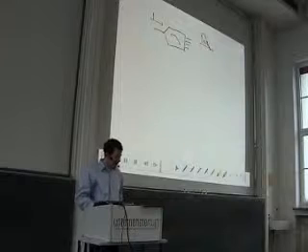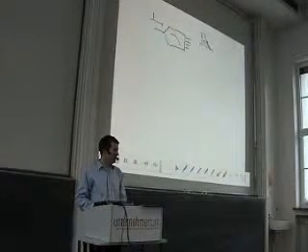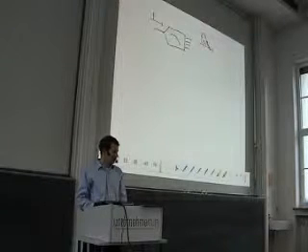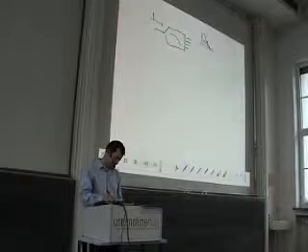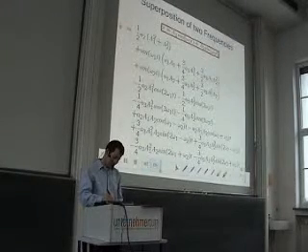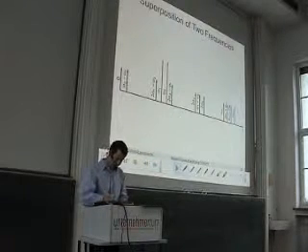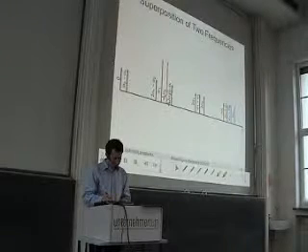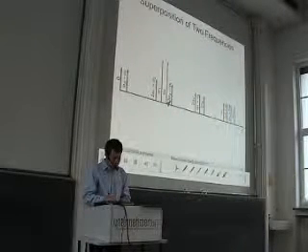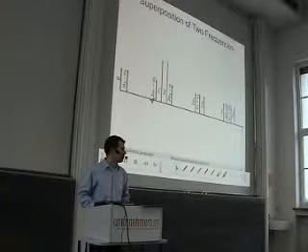And hence, people came up with another test, which is a so-called two-tone test, also called an intermodulation experiment. Let me go back to this slide. Here we saw if we have two fundamentals, then we get two components above and below the two tones.